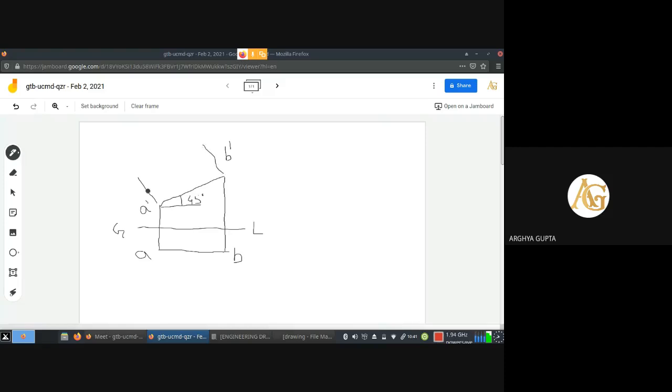Okay. Now a parallel line will have to be drawn parallel to A dash B dash, and at the middle it will be broken because we are showing the dimension in the unidirectional method, and two arrows will have to be given. All the drawings are not correct here because I cannot draw a straight line using a mouse. When you draw with scale and pencil, it will be easier for you. So that has to be written 100 horizontally always. Okay, is that understood?